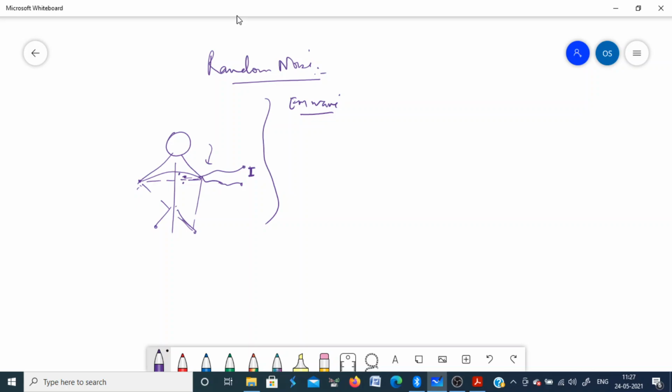Okay, and similarly, when you acquire some data from a patient, if he coughs, then due to coughing, the muscle noise, which is EMG noise, may get added to the ECG. Okay, so you are acquiring ECG from the patient, but if the patient coughs, due to the muscle contraction, another component, EMG, comes into the picture and it gets added to this ECG. So you have an ECG plus EMG mixture. Okay, so your objective now is to eliminate this EMG component from this ECG signal.